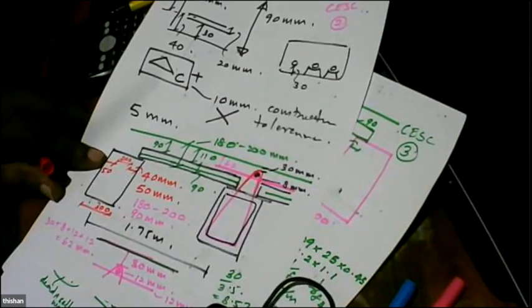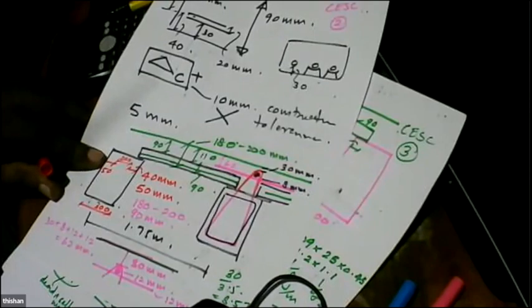So fatigue is not a major problem when it comes to concrete. Fatigue will be a problem only for steel. Somebody has asked, how to analyze the slab for 100 kilonewton point load. You can certainly use finite element, but because we are casting the slab in 2 stages, we have done the load testing and found the ratios that you have to use for load sharing. Because finite element can't handle that problem.